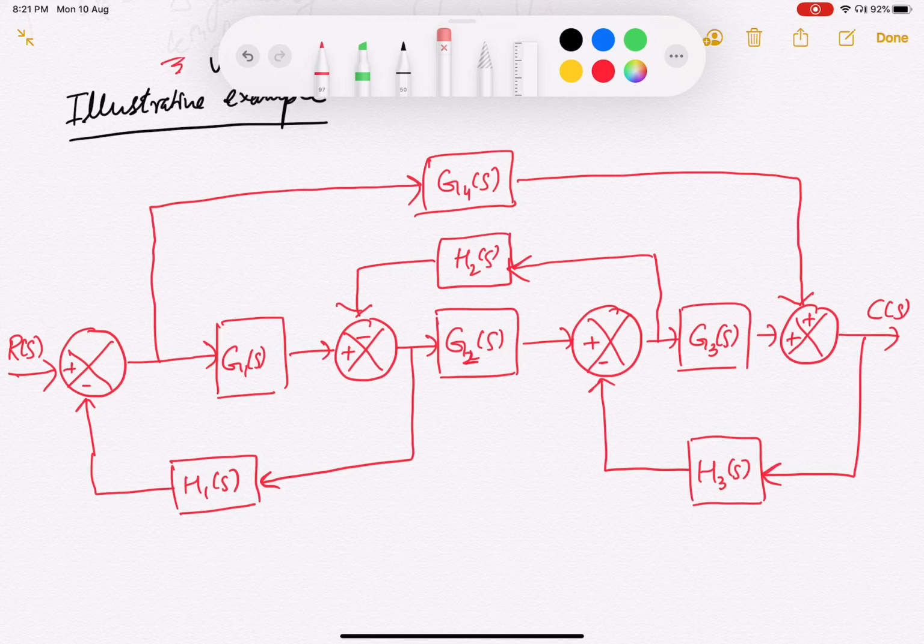So how would you make the signal flow graph for this system? For that, we have to label all the signals that you think are present. So wherever there is a processing of signals, just label. So for example, you have R(s) here, it is labeled. Here you can label this signal which is processed by G(s), you can call this X1(s). And then when you add this through the summing junction to another signal, here you'll have another signal X2(s). This X2(s) is getting fed to the feedback path, and you can have, say, for example, X3(s) here, right?